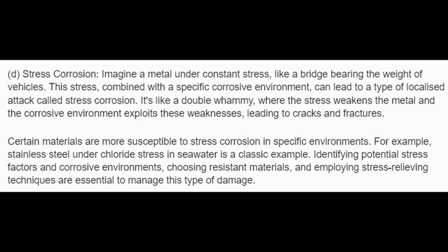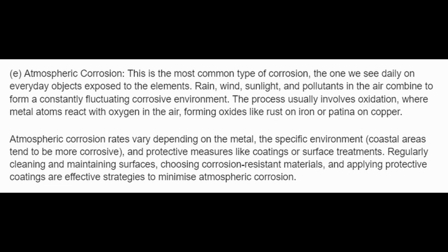Certain materials are more susceptible to stress corrosion in specific environments. For example, stainless steel under chloride stress in seawater is a classic example. Identifying potential stress factors and corrosive environments, choosing resistant materials, and employing stress-relieving techniques are essential to manage this type of damage.